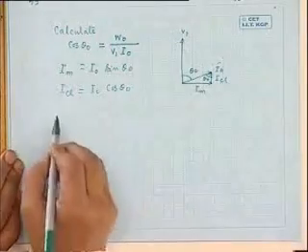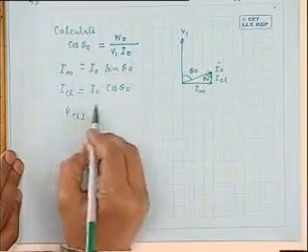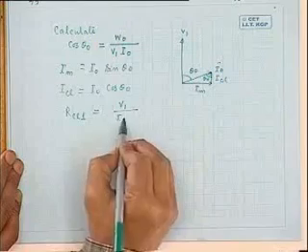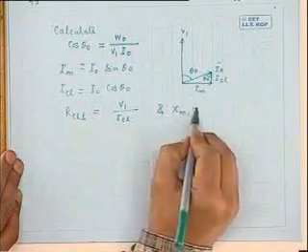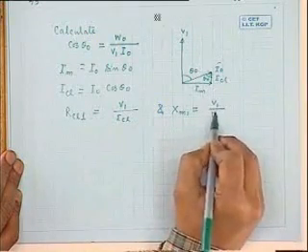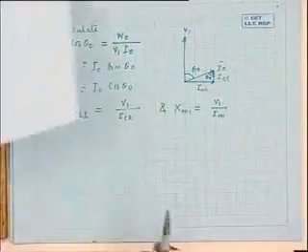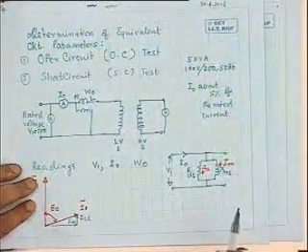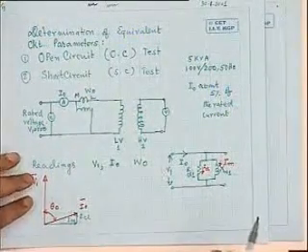Once you get this, then the calculation of RCL, which I will write RCL1 with respect to side 1, will be simply V1 by ICL, and XM1 will be simply V1 divided by IM. So from the open circuit test, you can calculate these two parameters, RCL and XM. The parallel branch parameters of the transformer can be calculated.